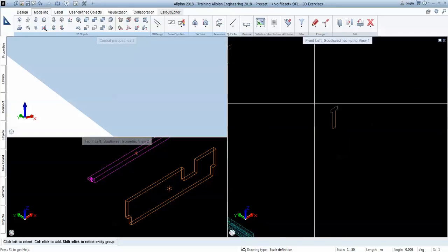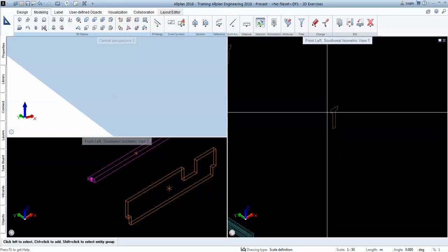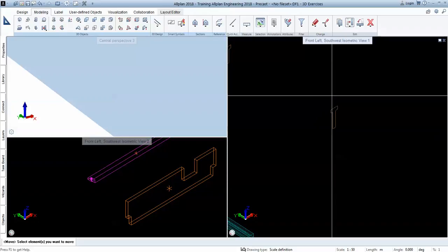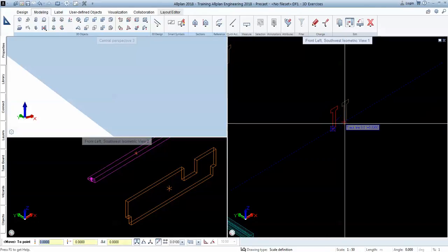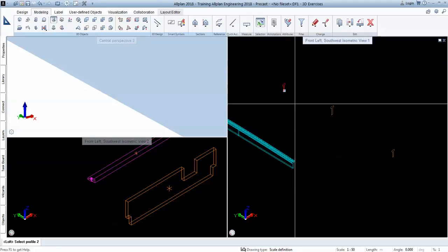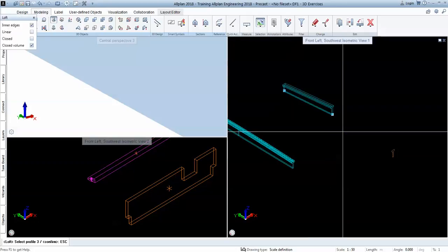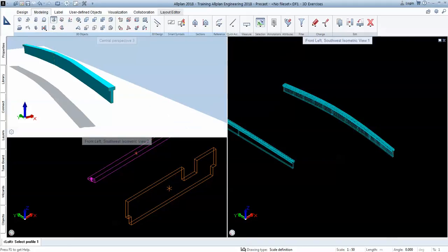And how can this be relevant or interesting is if you want to make different changes, you can even move this item. So I can move it like this, and the loft would still function. So it would go loft, select profile 1, profile 2, profile 3, and escape.